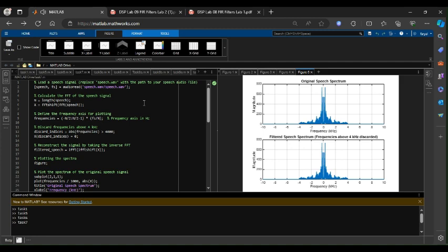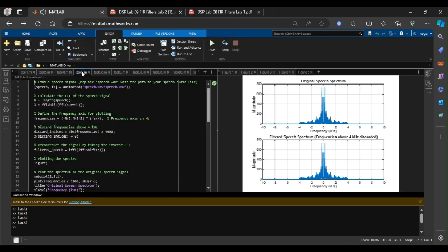So this MATLAB code implements an FIR, that is, finite impulse response filter for noise reduction. Here we have defined the array H, and these coefficients represent the impulse response of the FIR filter. Then we generate the original signal X, comprising sinusoid components at different frequencies, and Gaussian noise is added to this signal to generate a noisy version.